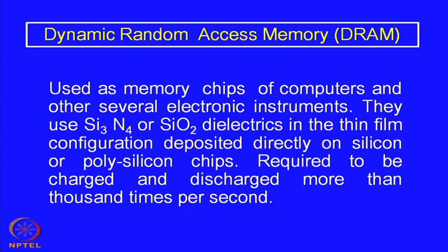memory chips are fabricated, and of course, the more recent advancement is in the area of changing the dielectric from silicon nitride or silicon oxide to barium titanate or barium strontium titanate based compounds. They are called FeRAM or ferroelectric random access memory. So, these are the few applications, very few in number. Of course, there are many other applications, maybe we will take them up in the next class when we discuss the ferroelectric and piezoelectric materials.